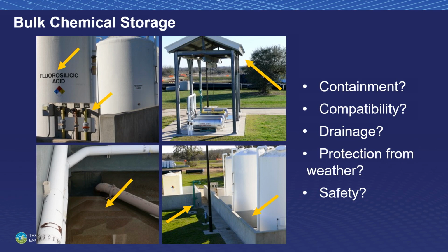Bulk chemical storage, one of the things that Don points out is that you need to have your bulk chemicals stored in a way that protects them from adverse environmental conditions. For chlorine cylinders, that either means enclose them or cover them with some sort of something to keep the sun off of them so they don't overheat, okay? Keep acids and bases separate in separate containment structures.